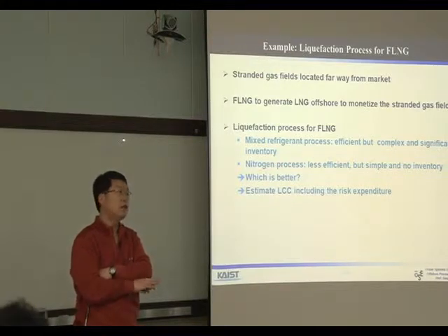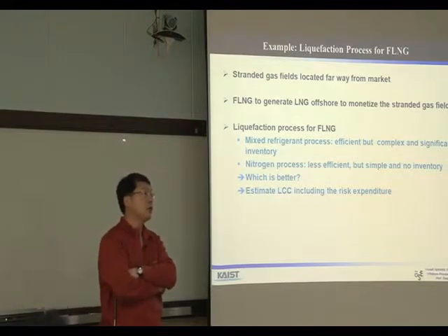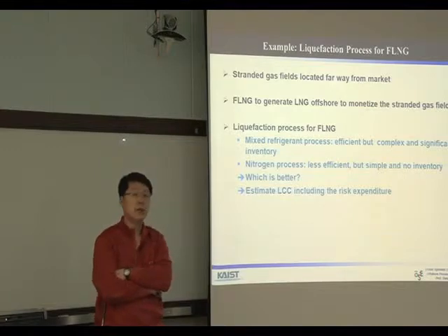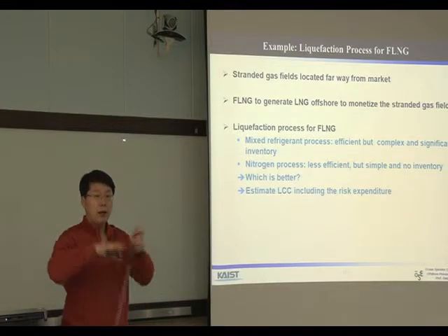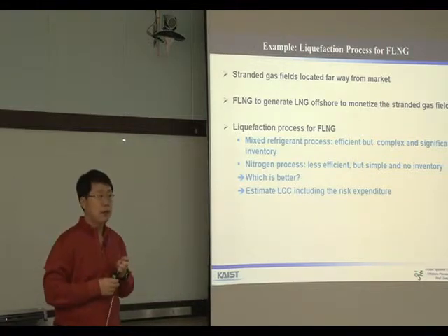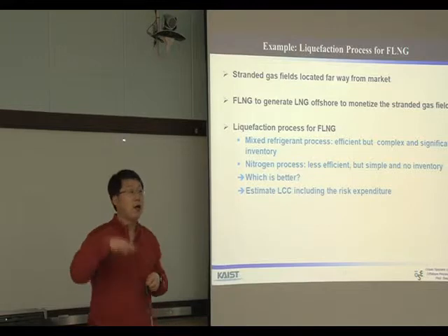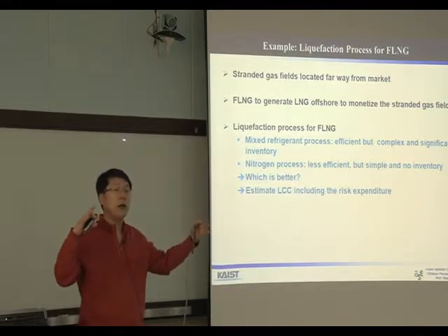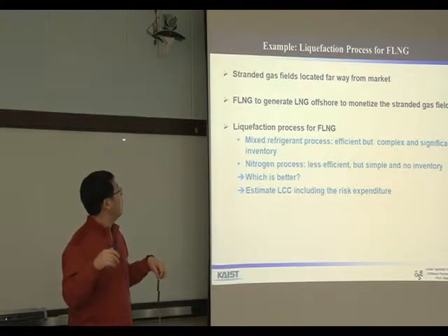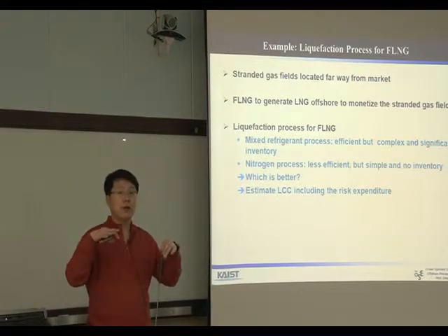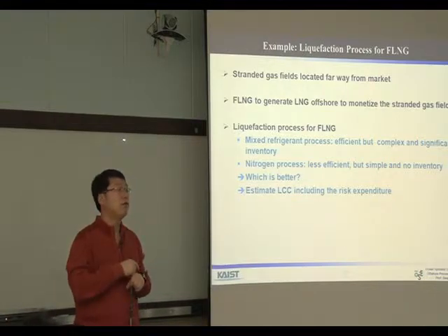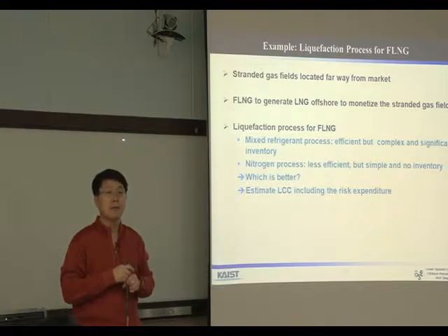Hydrocarbon inside the process, inside the equipment. The inventory means the amount of hydrocarbon. That means the plant is efficient, but the plant is complex. That means it is subject to a high failure rate and hard to maintain, and high inventory means it can have a higher fire and explosion risk.